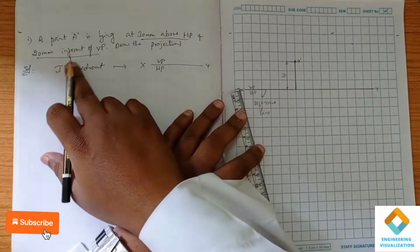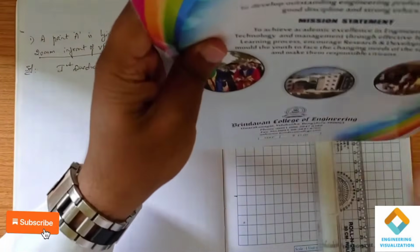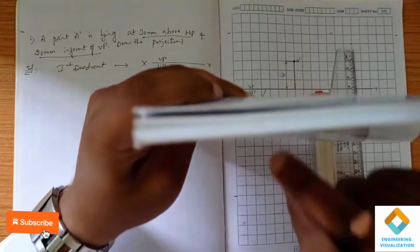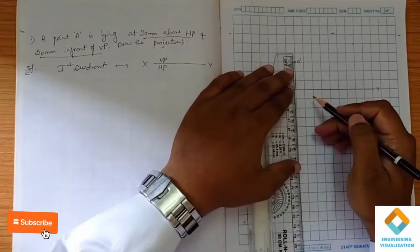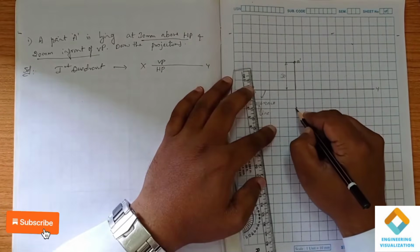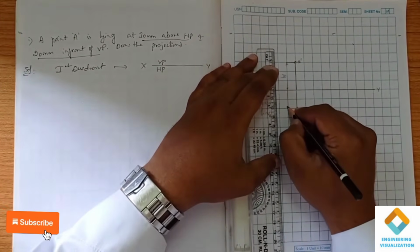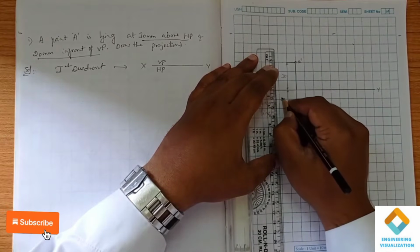So similarly we have to write the top view. You can see that it is 20 mm in front of VP. We know that if any point is lying in front of VP or behind VP, it means it is the top view. So it is 20 mm. So 20 mm means exactly we can count 2 boxes and draw a straight line, and we can put a point here. This is our top view. We can show the dimension line. Okay, this is 20.